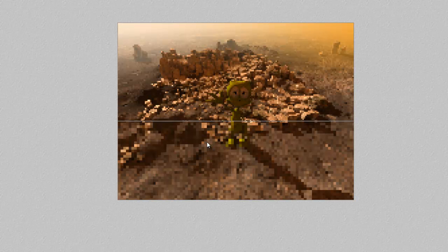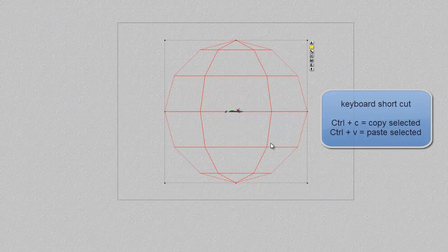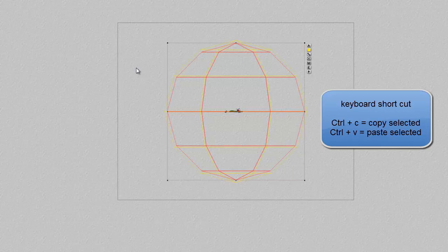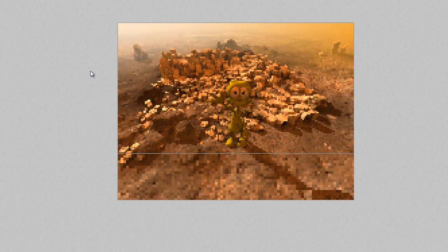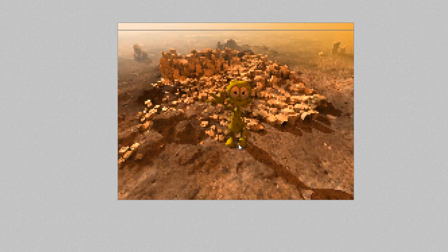If we want to create more of this ambient light, what you have to do is copy and paste the light source, then just make it slightly smaller so that the two sources aren't coincident, and then you can increase the amount of light that's being provided still further. So if you wanted to have a great deal of ambient light, that's the way to do it. You can't turn the effect up otherwise and still retain the colour that you've got.